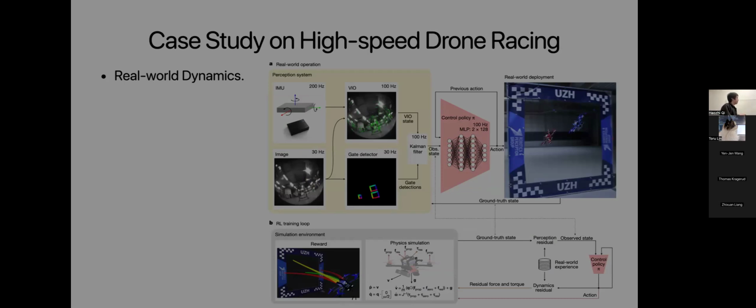The main difference in this work is what the authors observed when you want to push the limits to an extreme. With plain sim-to-real, basically you get some model and then leave it alone in the real world. No matter what happens, you do not change the weights. But in this case, one important part is they also collect some data in the real world. After you get a policy with reasonable performance in the real world, you can get some feedback from the real-world deployment to improve your simulations.